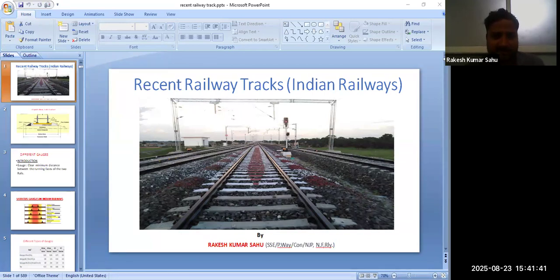Basically, the components start from subsoil, subgrade, then over it the blanket. Our formation is then ready, and we put ballast above it; the ballast, blanket and subgrade form our track foundation, and above it the track structure is formed. My part of work is basically related to the track structure, that is sleeper and rail.